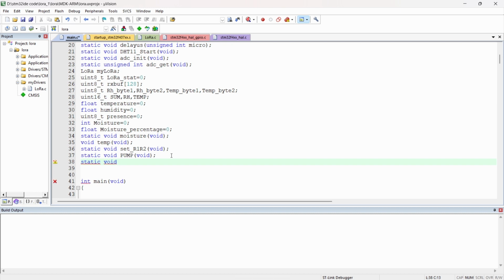This is going to be the independent watchdog timer. So we are going to configure only this independent watchdog timer. It will act independently without the help of the system clock, so that is what we needed. We didn't need to use the system clock. We have to use the watchdog timer's own clock, which operates even in the absence of the system clock.